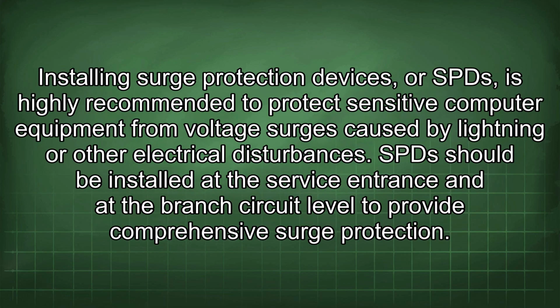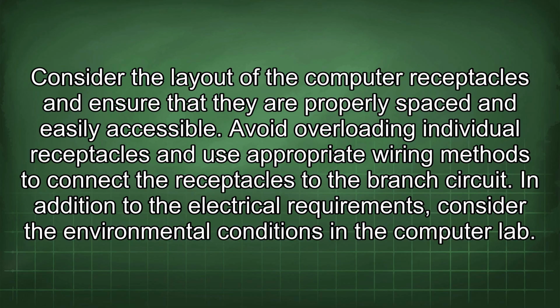Installing surge protection devices, or SPDs, is highly recommended to protect sensitive computer equipment from voltage surges caused by lightning or other electrical disturbances. SPDs should be installed at the service entrance and at the branch circuit level to provide comprehensive surge protection. Consider the layout of the computer receptacles and ensure that they are properly spaced and easily accessible. Avoid overloading individual receptacles and use appropriate wiring methods to connect the receptacles to the branch circuit.